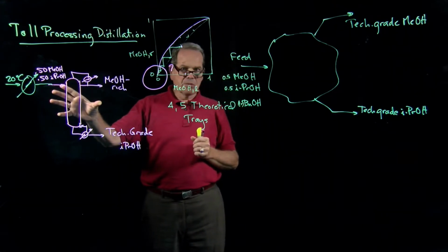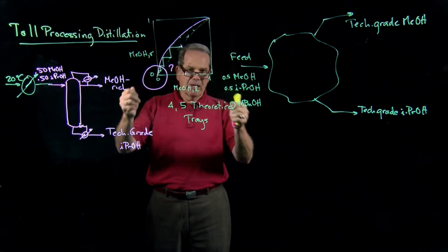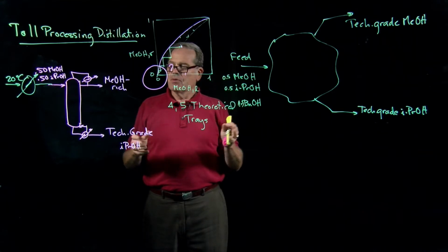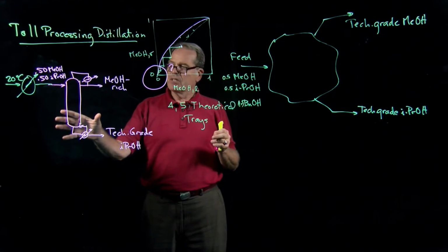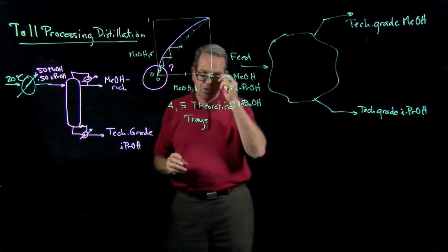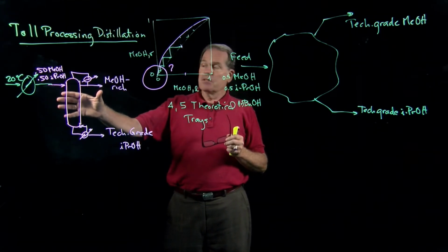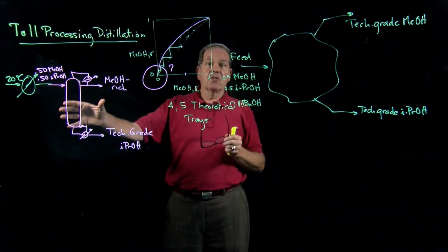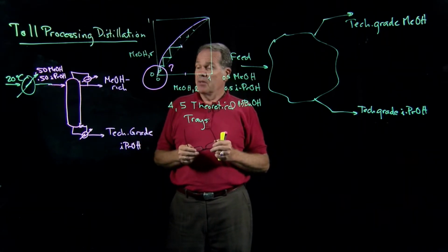I've already done that for this problem, so when we went into ChemCAD and started specifying keys and so forth, we had all the information we needed to properly specify this so that it ran the first time. That's something I really encourage you to do. Make sure that you do your homework and you have spec'd the column as best you can yourself before you go to ChemCAD, so that you have a good chance of a good simulation.